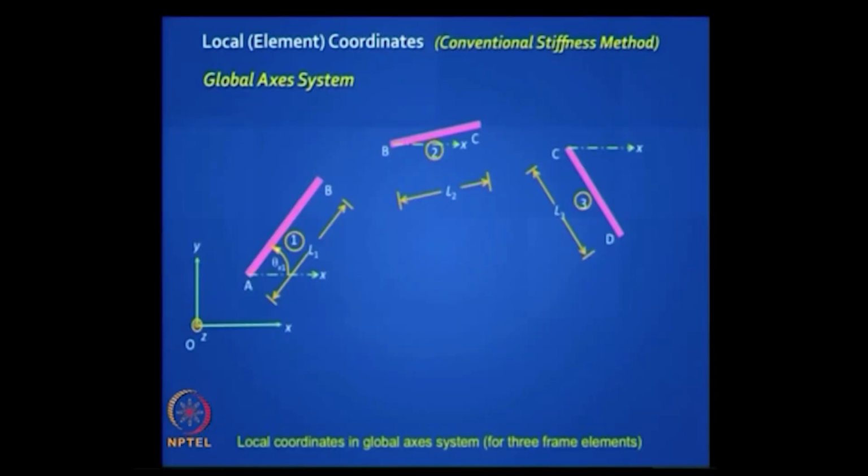The global, you can express the degrees of freedom both along the local axis, which is what we saw earlier, but you can also do it along the global axis. So for example 1, 2, 3, instead of pointing towards the local longitudinal axis 1, we can point towards the global x axis. Can you see that? So this is a big change. That means we do the transformation here itself. So I am not putting the star anymore.